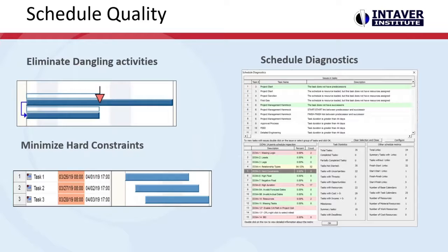So, schedule quality. The Monte Carlo simulation requires that you run hundreds of varying models of your schedule, which means your schedule must update automatically whenever dates or durations change due to risk or uncertainty. If your schedule is not optimized so that it updates automatically, the results of the simulation will often be overly optimistic, and I would consider them invalid.